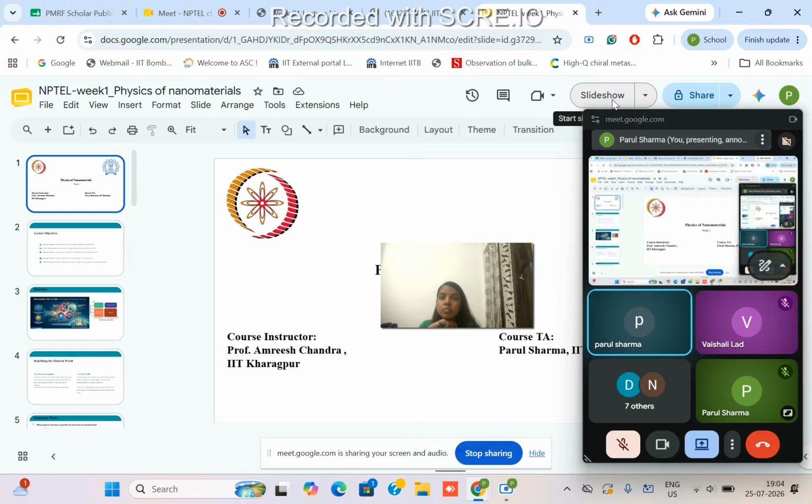Then what is the key feature of 1D nanomaterials? So first is isotropic behavior. So what were 1D nanomaterials? In two directions, the particle size is lesser than 100 nanometer. In one direction, the particle size is greater than 100 nanometer. So when the particle size is greater than 100 nanometer, obviously the properties will change in one direction. Because of that, it is no longer isotropic. Then it will start showing you anisotropic property. So 1D nanomaterials will feature an anisotropic property. So the correct answer is C.